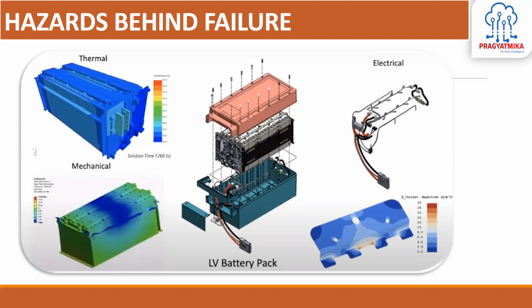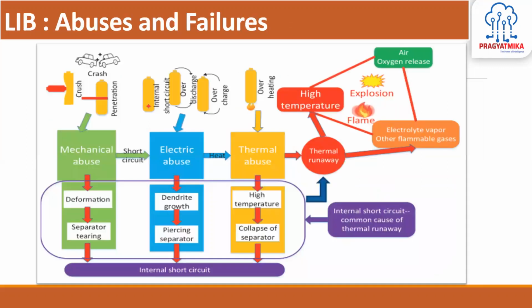So these are the big hazards in the design. Most people are not following this. They just go with what is available in the market, and it creates an issue. Like the casing available in the market, the bus bar available in the market, they don't do the calculations for this, and this is a very big issue. Even if you have done a very good design of your pack, there are still abuses that will happen to your pack, at the manufacturing end or at the customer end, and that will lead to loss of safety of your pack.